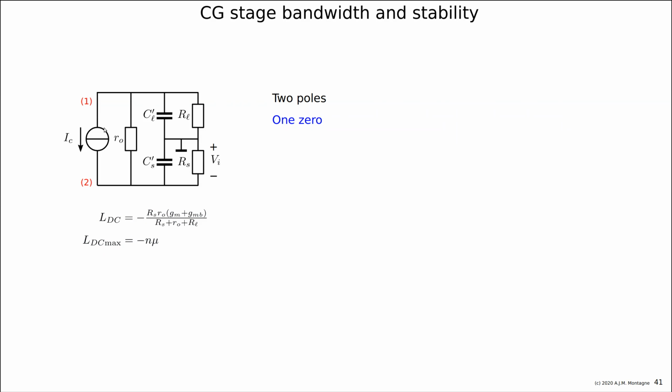And if there is, let's say, let's make RO infinite, then you see that the voltage VI is completely found from one pole and IC. But there is another pole in the circuit. This you cannot ignore. So there must be a zero on top of this pole to make it ineffective. So if RO goes to infinity, the zero that is in the loop coincides with one pole, and we have a single pole transfer. That is here, the conclusion.